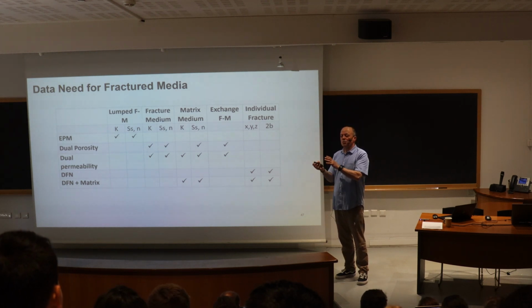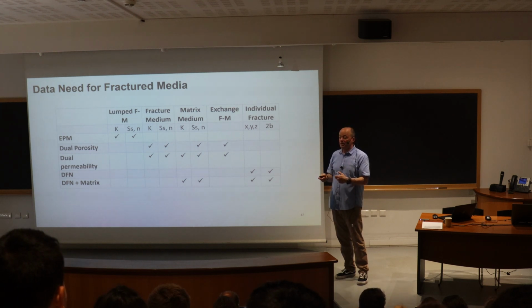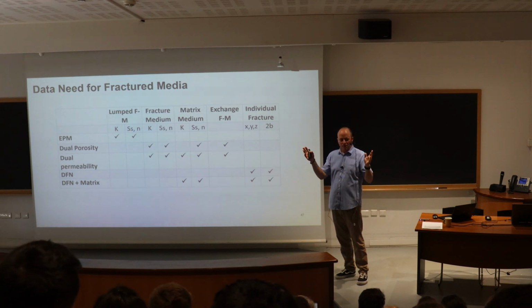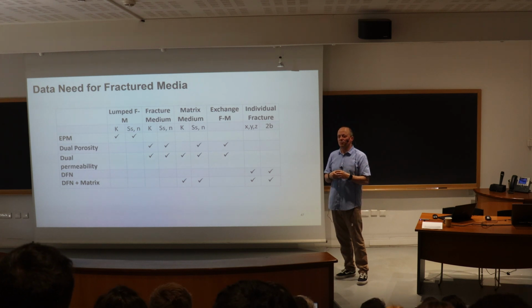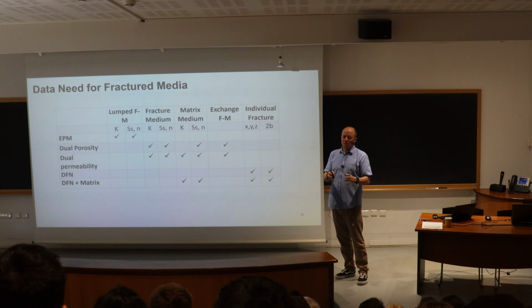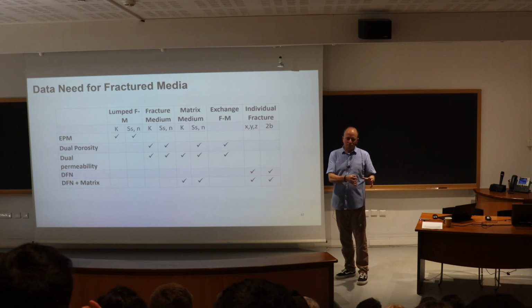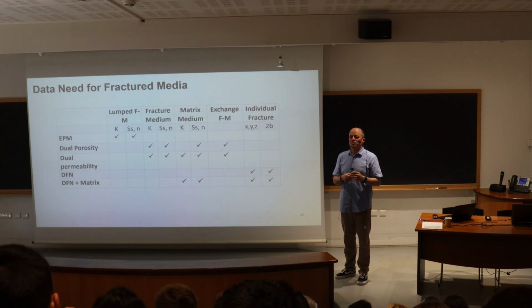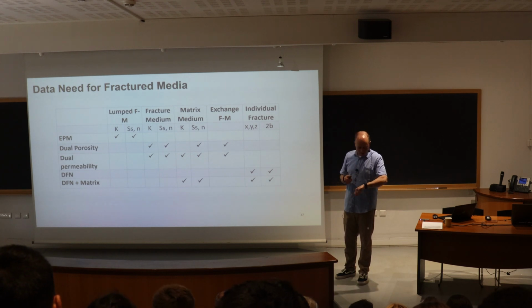So fracture zones, for example, that are quite thick, because from a computational point of view, to start putting every decimeter fracture into a model that covers hundreds of meters or perhaps 1 kilometer in scale becomes impractical. So you have to be pragmatic, use the information you have, do some averaging at a smaller scale, and try to keep the main features in your model.